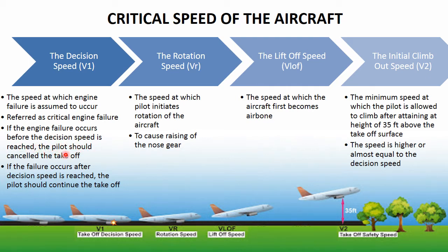So if we have an aircraft here, and the failure occurs before V1 is reached, the pilot should cancel the takeoff and it will go to the stopway.